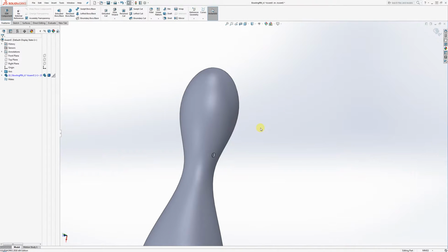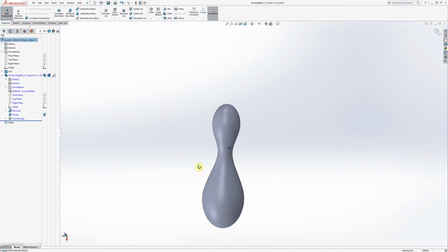And now the time has come to figure out, okay, well, how can I get this thing to spiral around the top of this brush handle? And I'll show you how I figured it out, okay? I went to my part file, and then I go, where's the plane that cuts it in half of this thing? There it is, right plane.